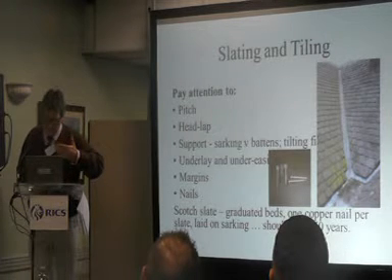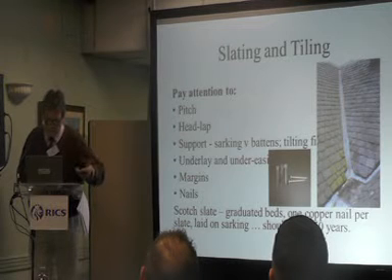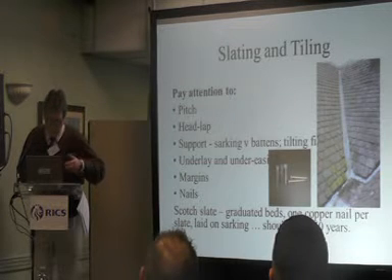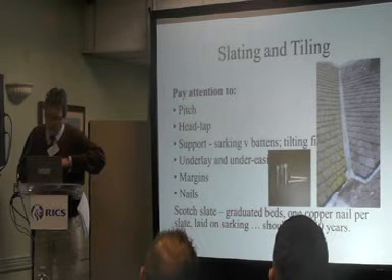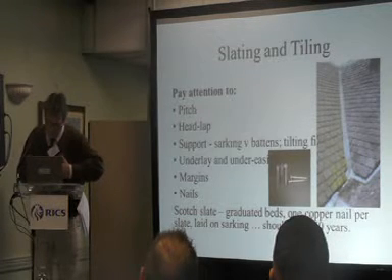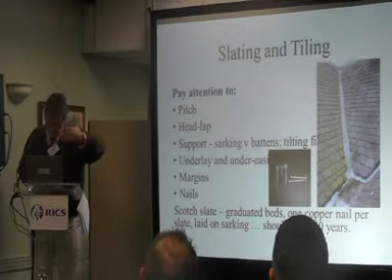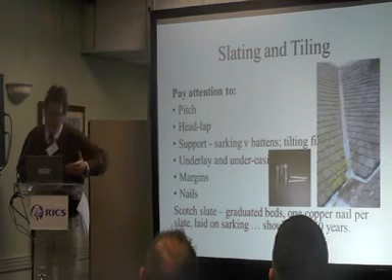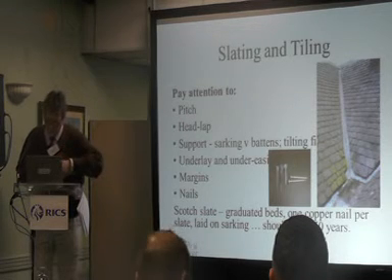Clearly, if you're not going to have a condensation problem in the roof, it needs to be breathable, so you need to use a breathable membrane. Tilting fillet, under eaves at the bottom, doesn't need to be breathable, it needs to drop into the gutter. What that's doing is taking all the water that does catch on the membrane all the way down and sliding it over a piece of standard roofing felt into the gutter.